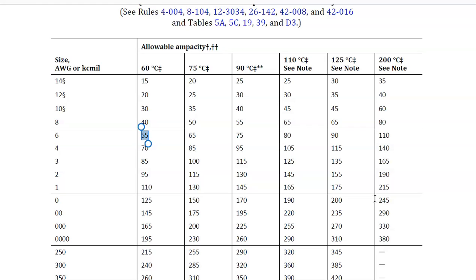If they give you a temperature, we use the temperature that is given. For these, if they say it's 75 degrees, the easy lookup is just to find your 75 degree column, carry that down, and track across till you hit that 50. It's bigger than the 48 amps that we need, so we're good to go. A conductor can always carry 100% of the current that is associated with it. Every single time. There's going to be some demanding on our demand loads that we will have for equipment. We'll cover those when we get there.